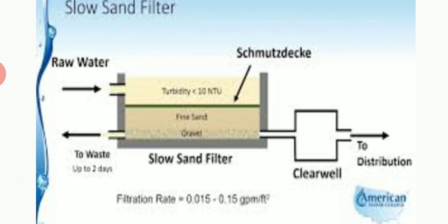The organic impurities in water become food to different microorganisms residing in the filter bed. The bacteria not only break down the organic impurities and convert them into harmless compounds, but also destroy each other and maintain a balance of life native to the filter. This is how biological action takes place. This is the third part of filtration. The fourth part is electrolytic action. This is another function of the filter.